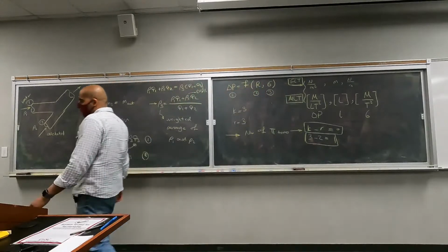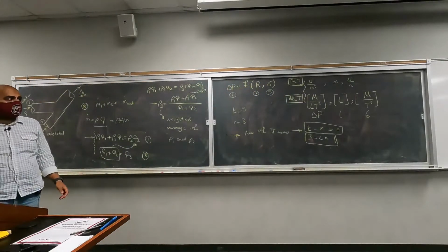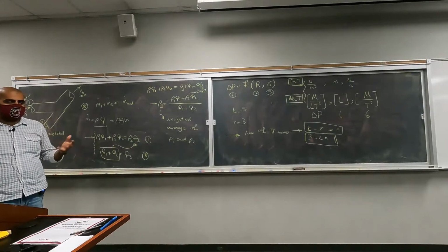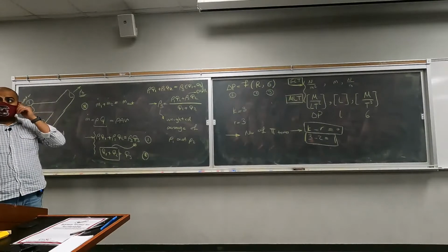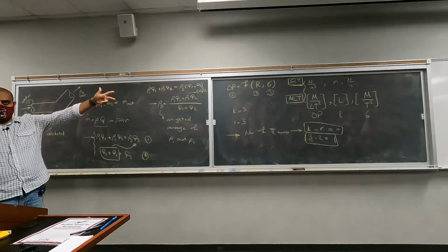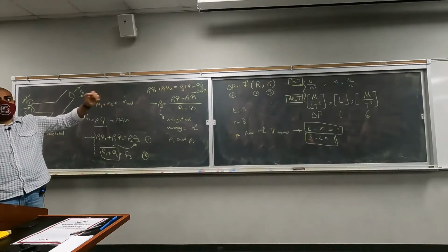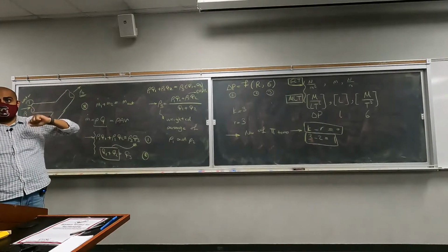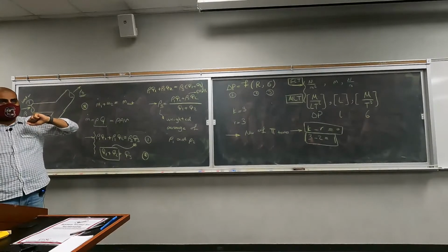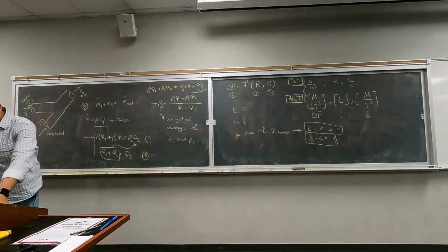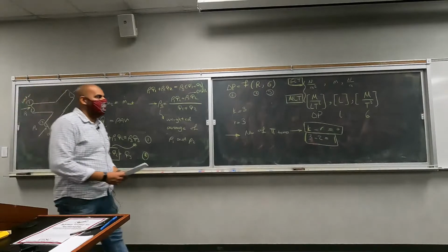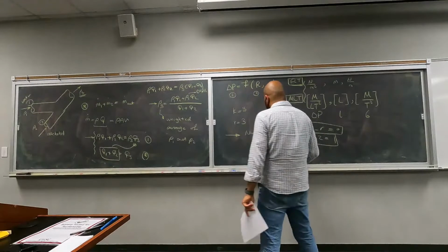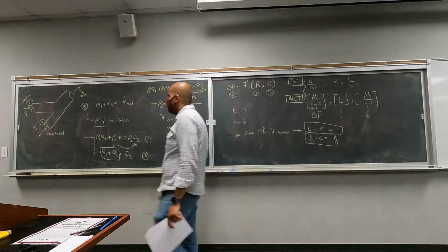What does this mean? This means that in general, if you were to use this Buckingham pi theorem idea anywhere, you have to check both of them, MLT and FLT, and take the maximum number. That will be the maximum number of pi terms you're going to get. But in an exam, you don't need to do that. I give you the type of problems that will give you consistent results, so you don't need to double check this.